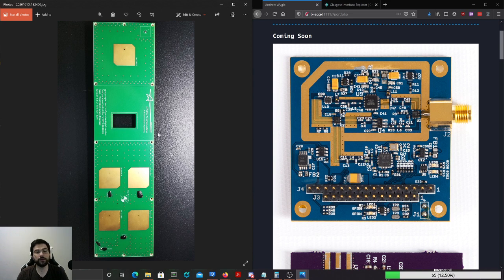Also, funny story, their board vendor built it upside down the first time. So the layer stack up is called out. You need this much spacing between these planes and so on and so forth. And they just swapped it. And so they spent like a week and a half in the lab. Like, why isn't this working? Our design, our simulations all say that it works, but it doesn't work. And then eventually they took a bandsaw and cut one in half. And they were like, oh, that's why it doesn't work. It's built upside down. So that was great.